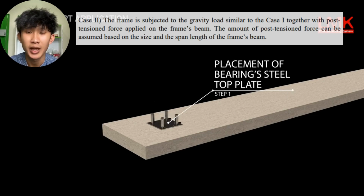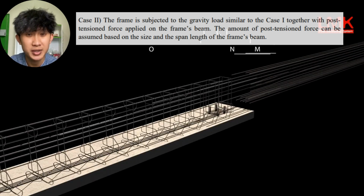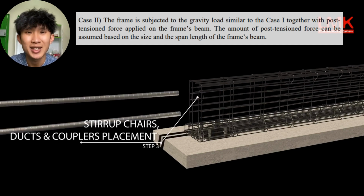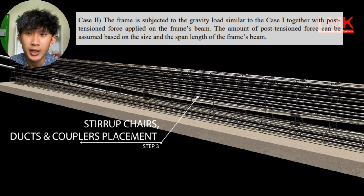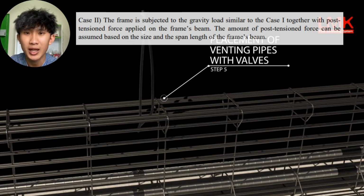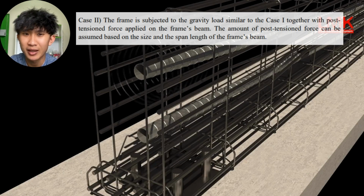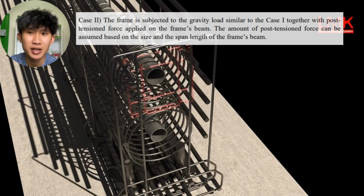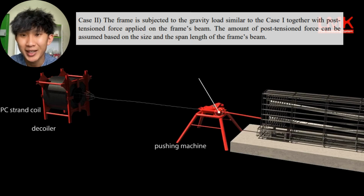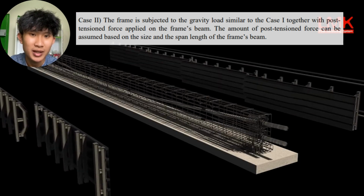I'm Yang, and I'll be discussing case 2, where the gravity load is similar to case 1 together with post-tension force applied on a frame's beam. Post-tensioning is a technique used to strengthen and reinforce concrete structures by applying tension to steel tendons or cables after the concrete has been cast and cured. This process helps to counteract the effects of bending forces and increase the load carrying capacity of the structure, which helps to reduce the overall tensile stress in the concrete, particularly at the bottom of the beam where the tension is highest, leading to a decrease in bending moment.